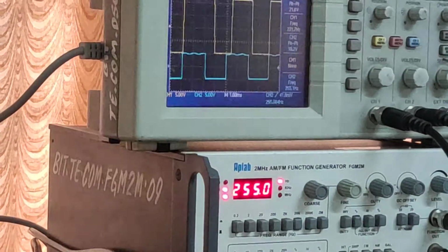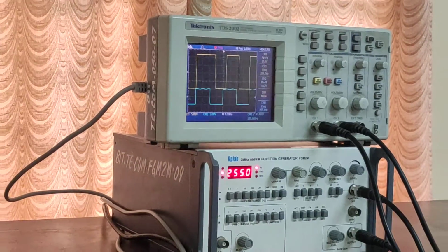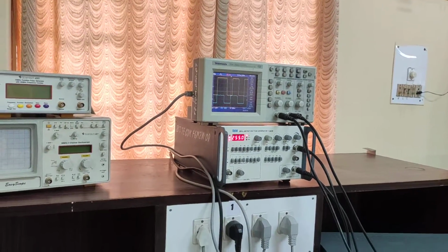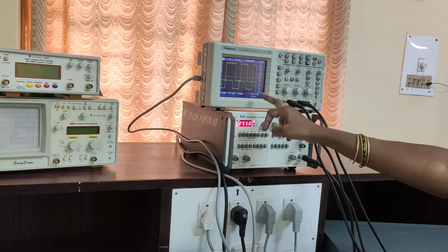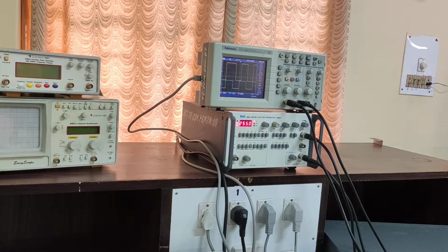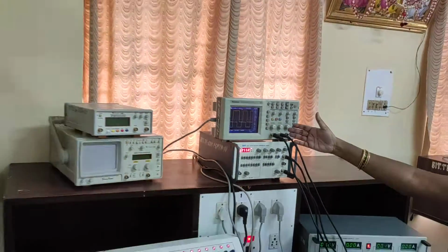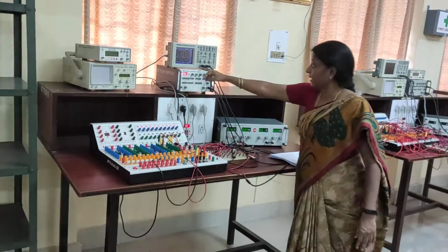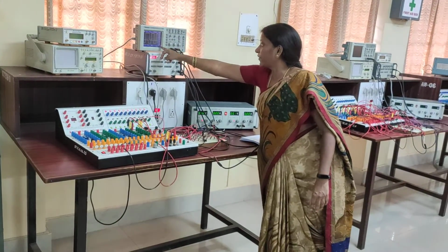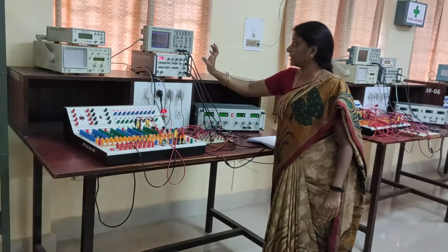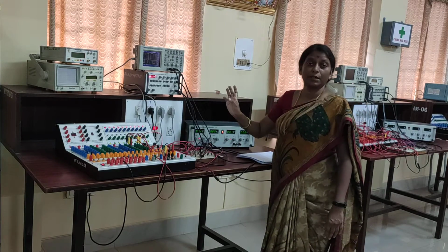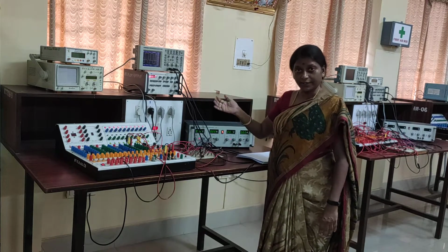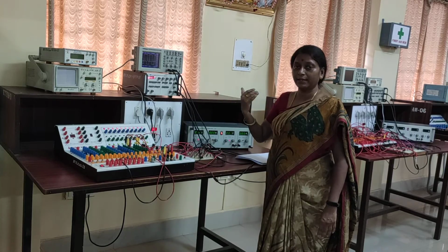Since we are using a comparator of 12 volts and minus 12, so approximately 90% of the signal will be given as a plus and minus V saturation. So it is equivalent to what we have given as a binary input. So this is the detection of the ASK, which is having the same frequency, approximately the same frequency with changing amplitude. Okay. This is the ASK generation and detection using the transistor and envelope detector.